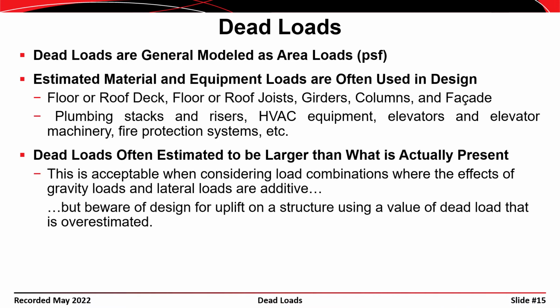However, it's important to bear in mind that sometimes the dead load acts as a restraining force. If you consider the overturning force of the wind or a seismic action, then the dead load actually helps resist the structure from toppling over or from sliding. So if you overestimate the dead load, in some cases it might be unconservative.